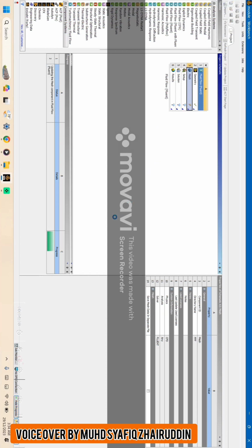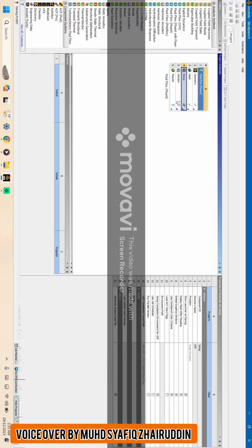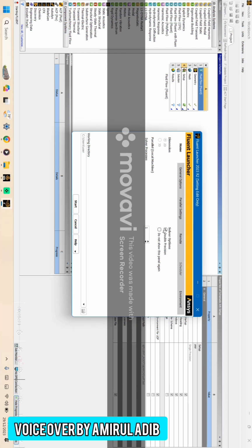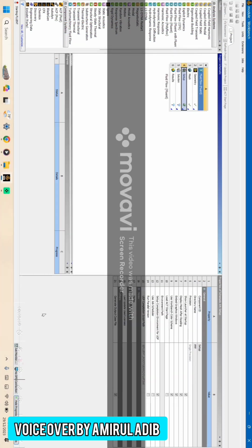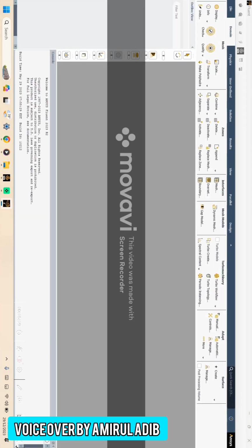and then you go to the workbench, click mesh and update the mesh icon, and we will wait for the progress until done. Okay, now the mesh and geometry are done, ready to solve. We click double precision and click start. The solver processors is the number of processors your computer has. If your computer supports more processors, add more to the solver processors.